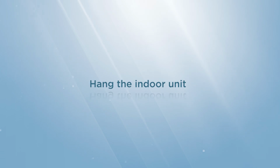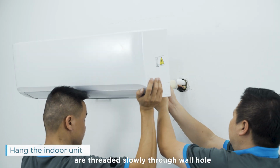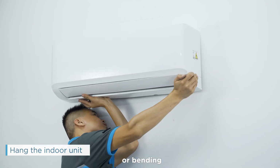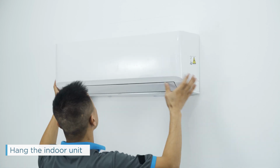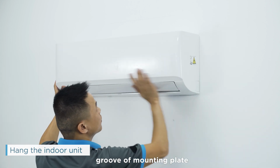Hang the indoor unit. Copper pipe and connecting wire after wrapping are threaded slowly through the wall hole to prevent colliding with the wall or bending. Hang the indoor unit on the hook of the mounting plate. Insert the lower part of the indoor unit into the groove of the mounting plate.